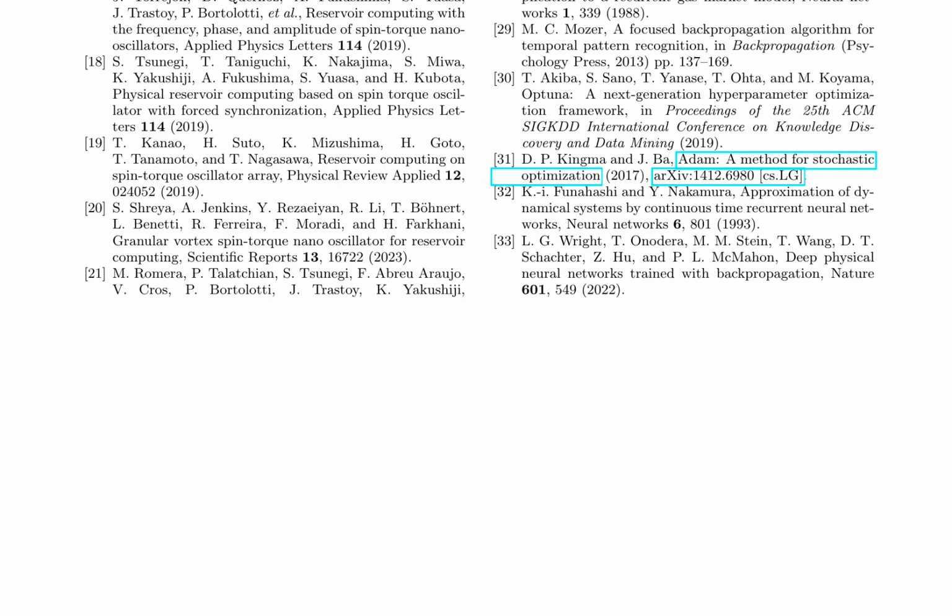Multilayer spintronic neural networks with radio frequency connections have been demonstrated, and dynamical neural networks based on spin transfer nano-oscillators have been proposed. Theoretical frameworks, such as nonlinear auto-oscillator theory, have been applied to understand the behavior of spin-polarized currents in microwave generation.